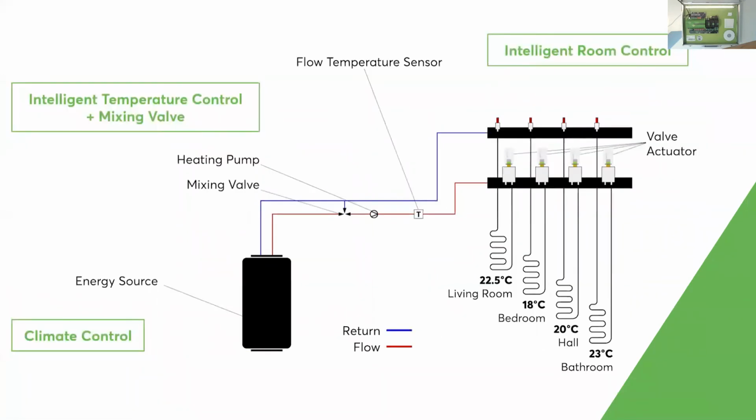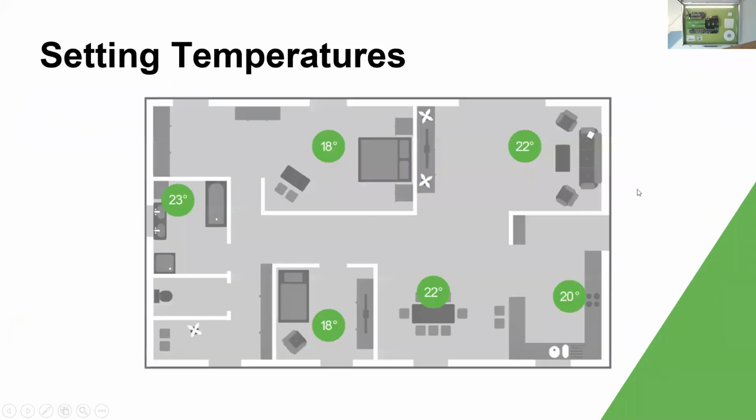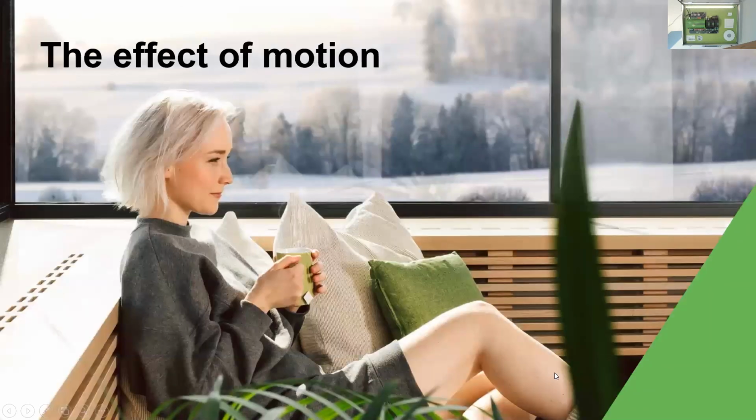So that was our layout that we've done, and we've done a bedroom and a kitchen in this layout. But other than that, we've done everything the same. Climate controller for the boiler, mixing valve controller for the mixing valve that contains the temperature sensor, and an intelligent temperature controller for the zone valve. Different temperatures in different rooms of the house at different times of the day. Schedule in each room, temperature in each room, warm living room, cool bedroom. Perfect, exactly what we want.